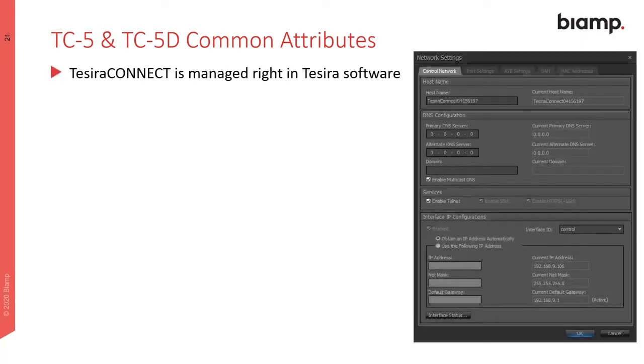Okay, so this is the dialog or the wizard and the network settings of the TesiraCONNECT. As you can see, in the control you can change the host name, you can change the IP address of the control port or the media bridge port. So if you have a separated network, if you need to separate the AVB and the control, then you have to be in the separated mode, which is enabling the AVB media in your TesiraCONNECT 5.